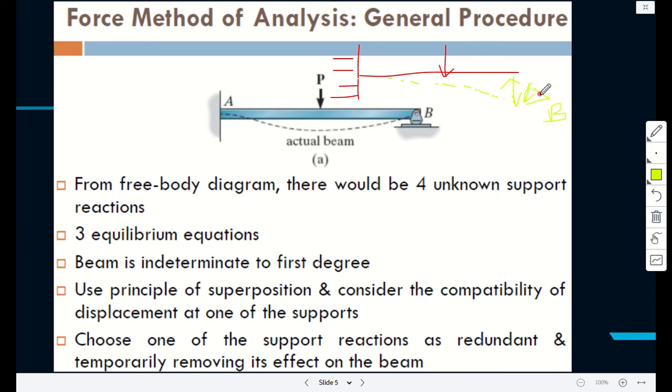All right, so this is the first part. In the second part, because this is now statically determinate, you can actually use the three equations to solve as well. Again, this is structurally determinate. Here we apply RB, and of course this one will also deform in some way, because you're pushing it up, and the movement there will be due to RB.